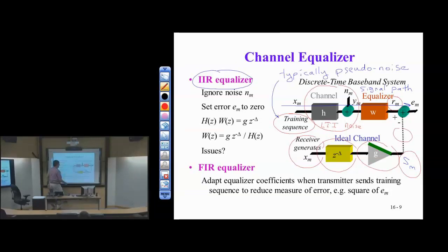And the delay can also take care of it if I let the delay be long enough. But I can correlate at the input to the receiver against the PN sequence that I'm looking for to find out what the delay is. I look for the peak. So that's one way that I can line up. If I were to do that, I would insert a delay before the equalizer just to line up and synchronize the sampling time.